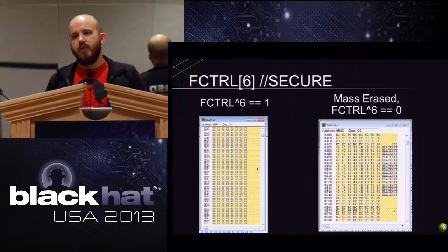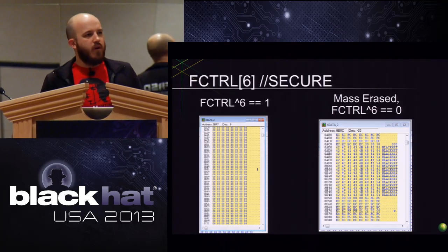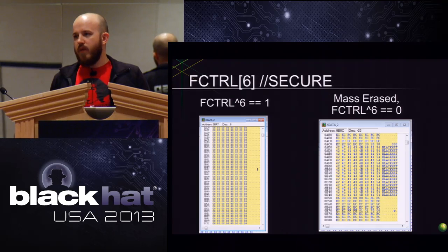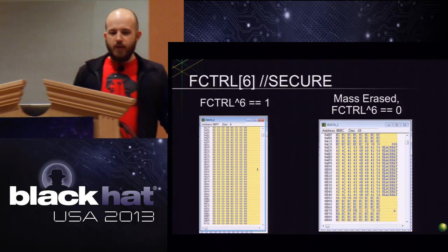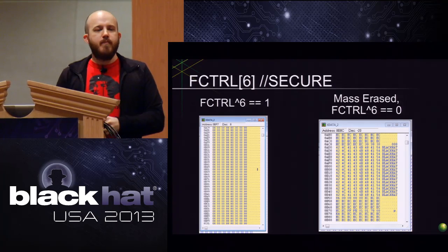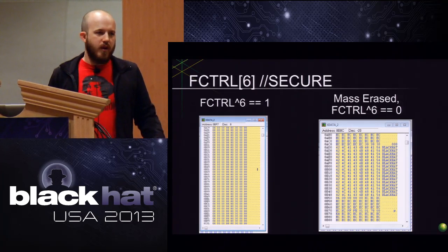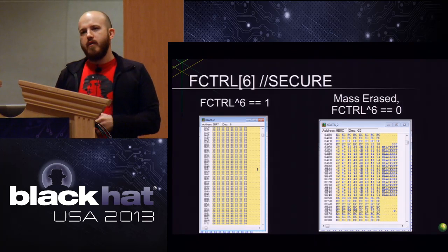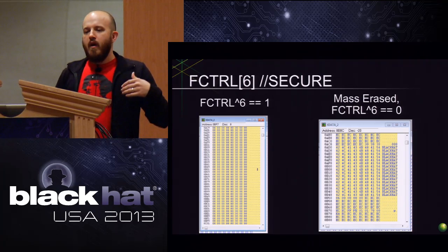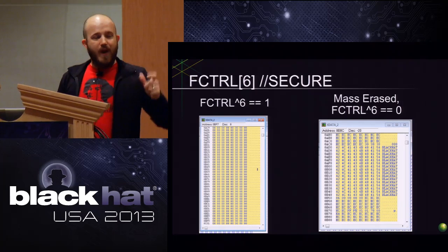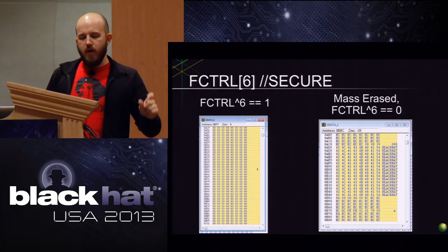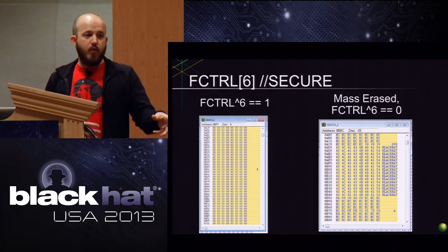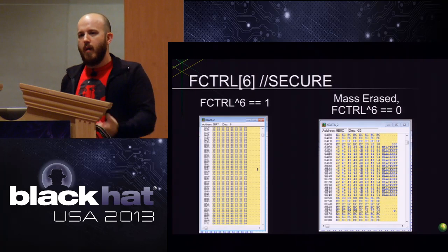that may or may not matter depending on the particular use case. This is like being able to see RAM without being able to see the code, so you don't necessarily have any context to know what these things are, outside of knowing what the device does. Let's say it's a smart meter, and it's doing encryption as part of an ANSI standard. Well, you know certain things about how that's going to work: what type of encryption it uses, what its key sizes are, things like that. And coincidentally, the way that's implemented in code will most commonly require you to copy that key out of code memory into RAM to then perform operations on it.